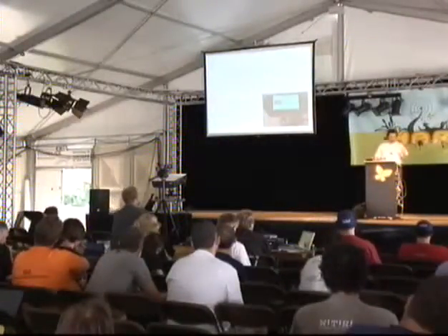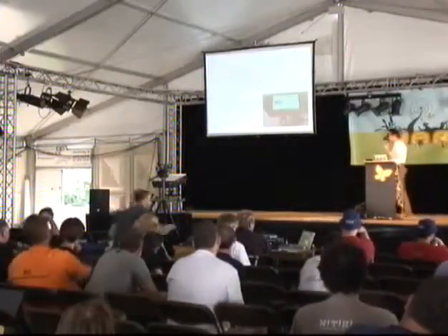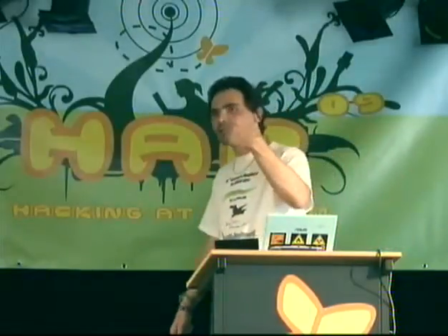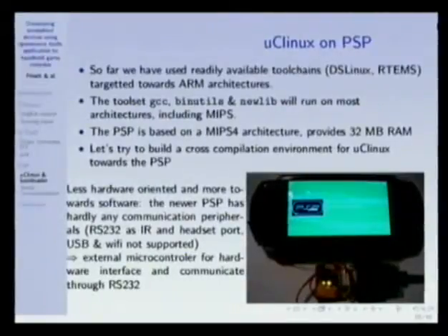And one thing that I emphasize in teaching embedded devices is don't be limited by the tools you have available. When you're using proprietary tools, you're spending a few $1,000s on a compiler, and the day you want to switch to another project, you will select your new hardware depending on the compilers that you have. If you learn how to use the trio GCC, binutils, and uClibc, you're no longer limited by the hardware because this set of tools will simply cross-compile Linux or any kind of software to whatever CPU you're familiar with: Alpha, Sparc, MIPS, ARM, of course x86, Intel.